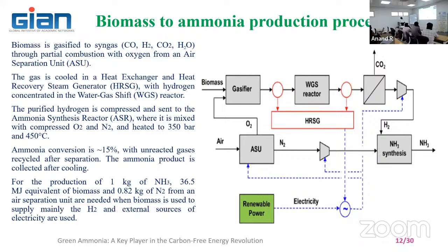Then the gasifier has several applications. The gas comes out at high temperature or low temperature. If you are going for updraft gasification, you take the gas at the top, and the temperature of the gas is around 400 to 500 degrees centigrade, so you should not use it directly. Suppose you want to use the gas for engine applications. Then you cannot use the gas coming out from the top, because at high temperature it carries tar. When you allow the gas into the engine intake manifold, it is going to be deposited on the components of the engine.